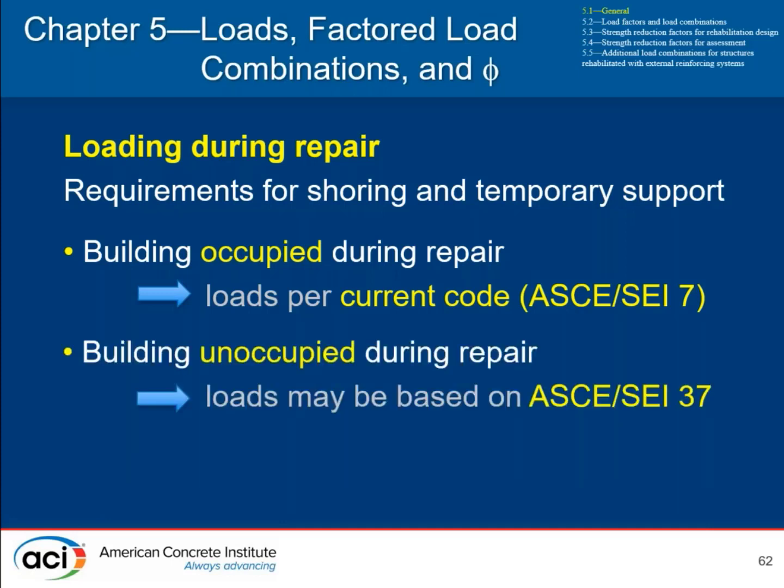If the structure, or any portion of the structure where the work is performed, is unoccupied during the construction period, then less stringent temporary design loads could be specified using ASCE/SEI 37.